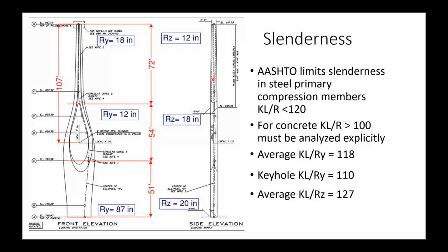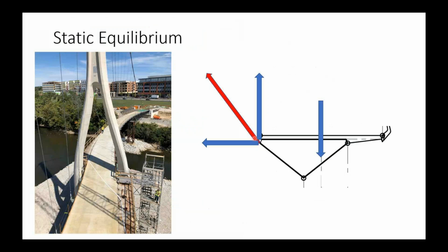At service demands, I like to have the buckling load be 20 or 30 times the service demand on the pylon, which puts you at 10 or 15 times the demand at factored loads. But that's just a comfort level. Again, I don't want to get anywhere near the case where I'm possibly buckling an element like this, which the whole bridge relies on.